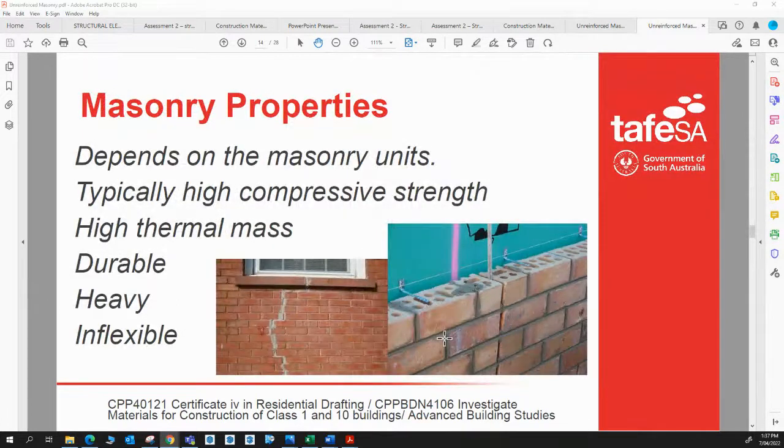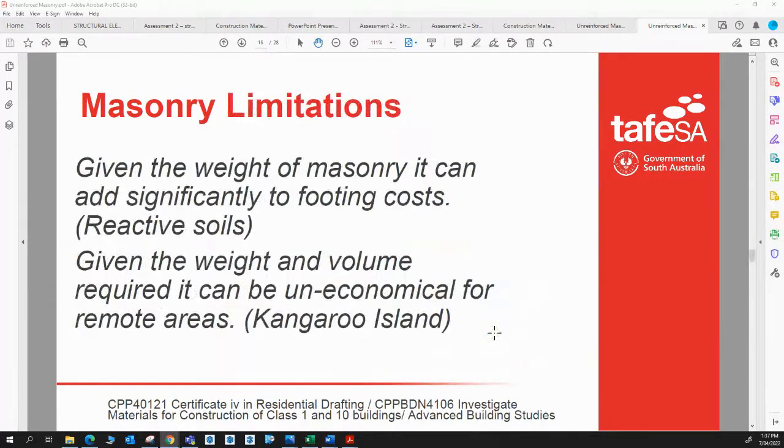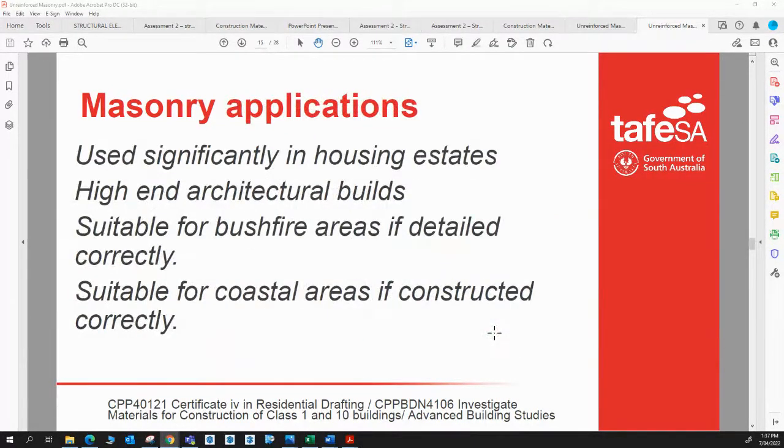Beyond that, of course, brickwork is vulnerable at its brick control joints, and your foam infills to that are vulnerable. But another way of doing a brick control joint is to put a 10mm backing rod, or we'll use a 12mm backing rod so it squeezes down a little bit in here, and then have a fireproof mastic over the top of that.